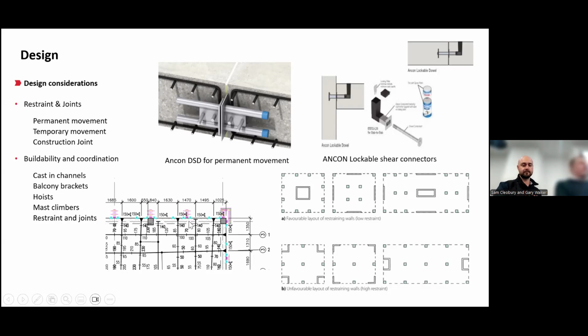We've built and designed lots and lots of buildings, as all PT contractors and designers have, and we can coordinate around anything as long as we know it's there. When we're doing our design, if it's there, we put it in our drawings and we'll coordinate around it. Our live ends are relatively flexible, probably more flexible than the cladding and fixing points for balconies and things. So we always like to go second. If you give us what you've got around your slab edge, we'll coordinate around it.